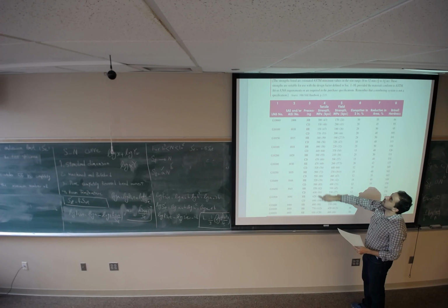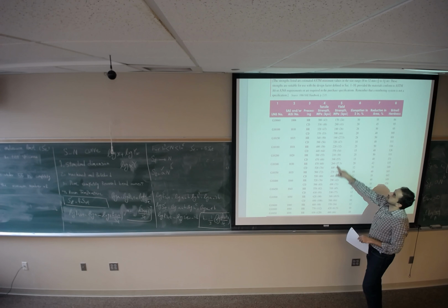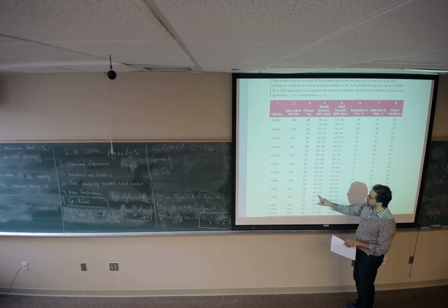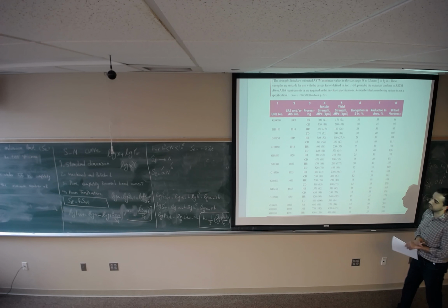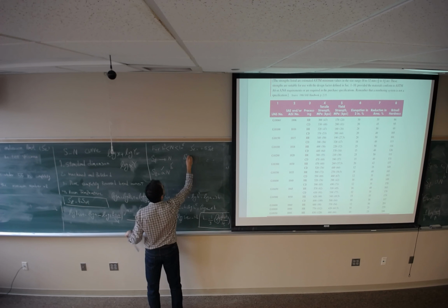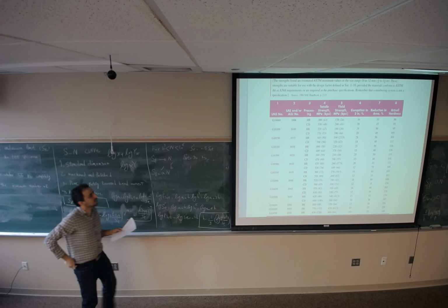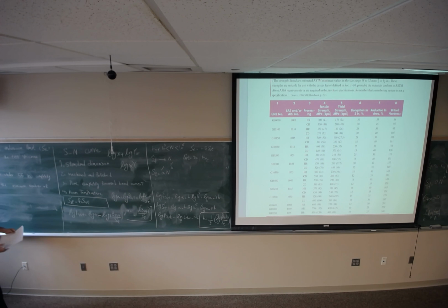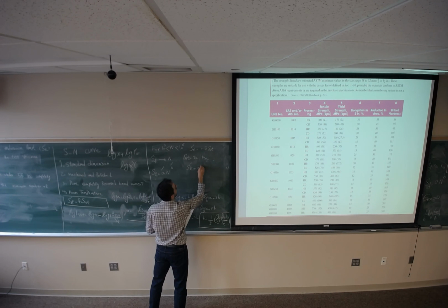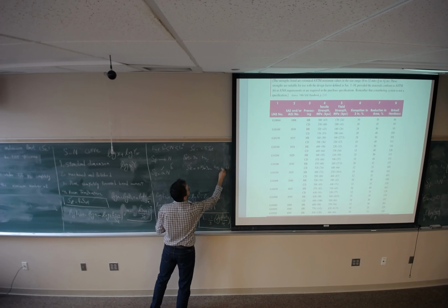This column is tensile strength, which is S ultimate. This is for yield strength, which is Sy. We are looking for S ultimate. For 1050 hot roll, it's going to be 620 MPa or 90 kpsi. So S ultimate is 90 kpsi. 90 is less than 200 kpsi, so I can use this. S'e is 0.5 times 90, which is 45 kpsi.